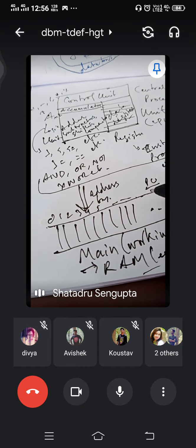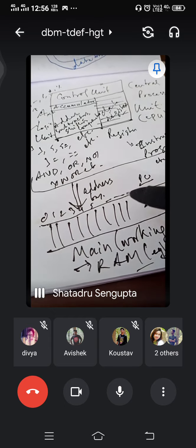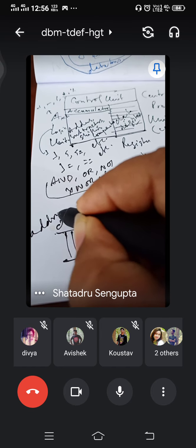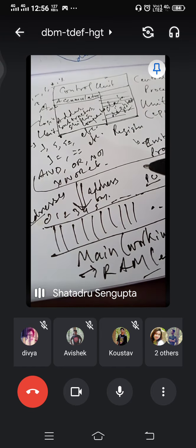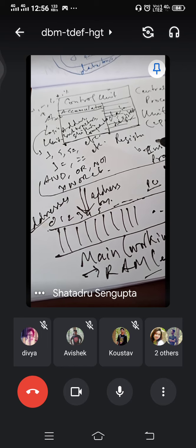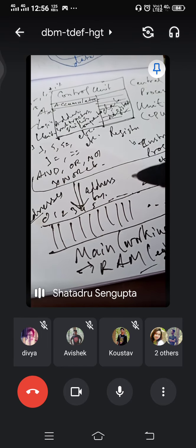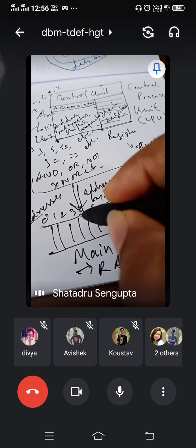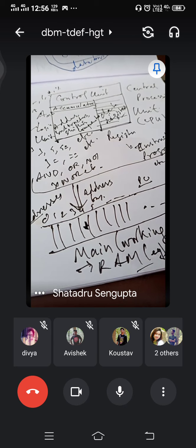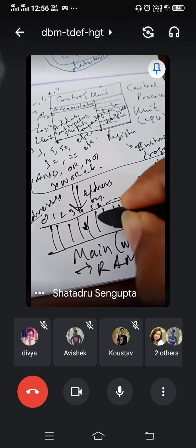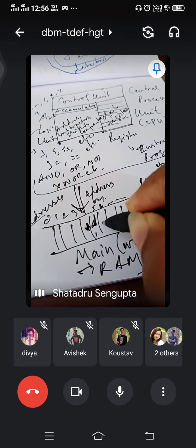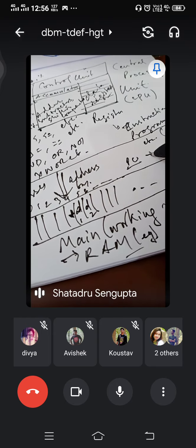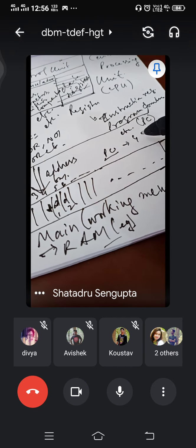Now these line numbers are the memory addresses. These are called the addresses. Now let us say that in the program, obviously this is run by a program, it is mentioned that the first instruction is coming from some place, say here. Then it has two data. Let us say they are at 5 and 6, D1 and D2. Then the program counter will act like this. It will be loaded with 4. Okay.